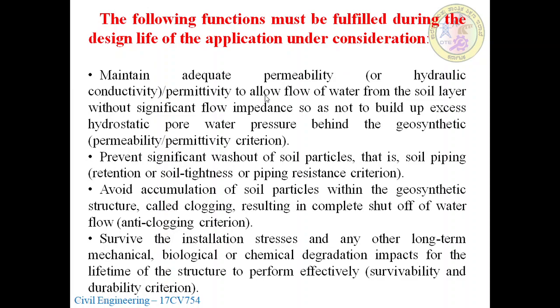Prevent significant washout of soil particles, that is soil piping. Avoid accumulation of soil particles within the geosynthetic structure, called clogging, resulting in complete shut-off of water flow: the anti-clogging criteria. Survive the installation stresses and any other long-term mechanical, biological or chemical degradation impacts for the lifetime of the structure to perform effectively. So these are the survivability and durability criteria.